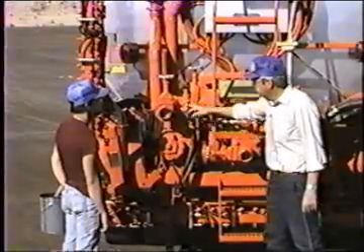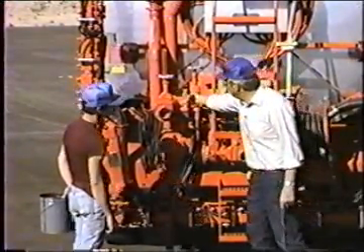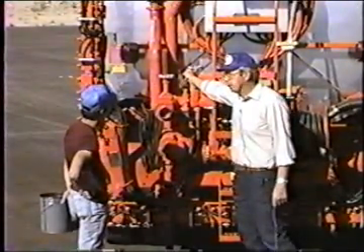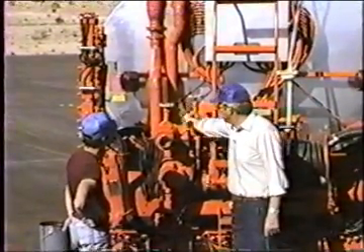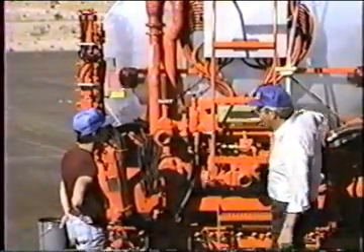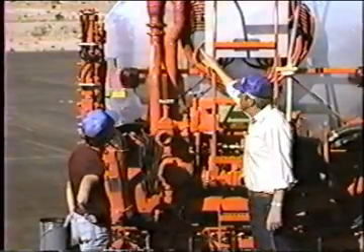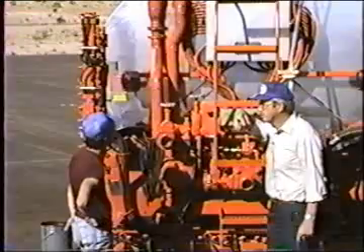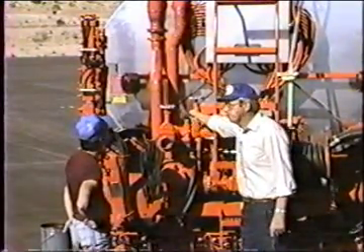The pump's in reverse. It's pulling in the top and pushing out the bottom. Now obviously it's going to try to pull material out of the spray bar because that valve is open. We have been circulating. We have been spreading, so that valve is open. Okay, it's going to try to pull it back out of there, but at the end of that valve, if you trace that all the way through the circulation path, is that relief valve. And that relief valve is just like a check valve. We can push through it, but we can't pull back out of it. So it can't pull anything back out of here. No need to close this valve.